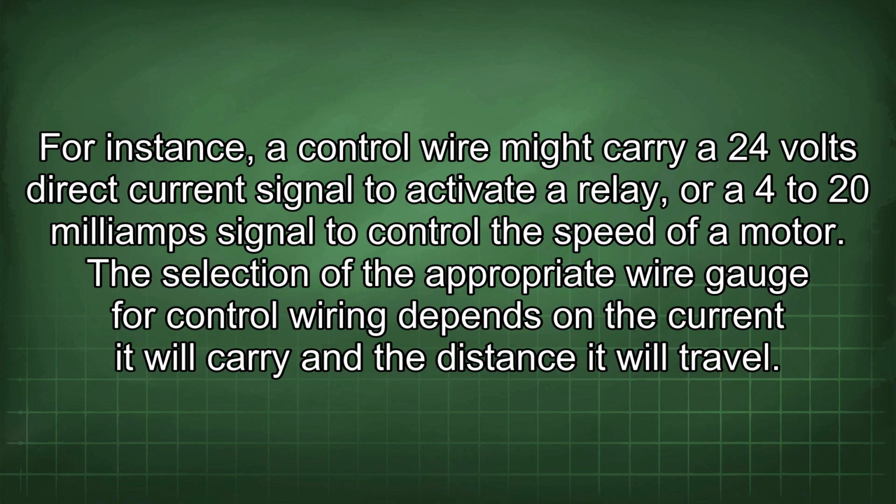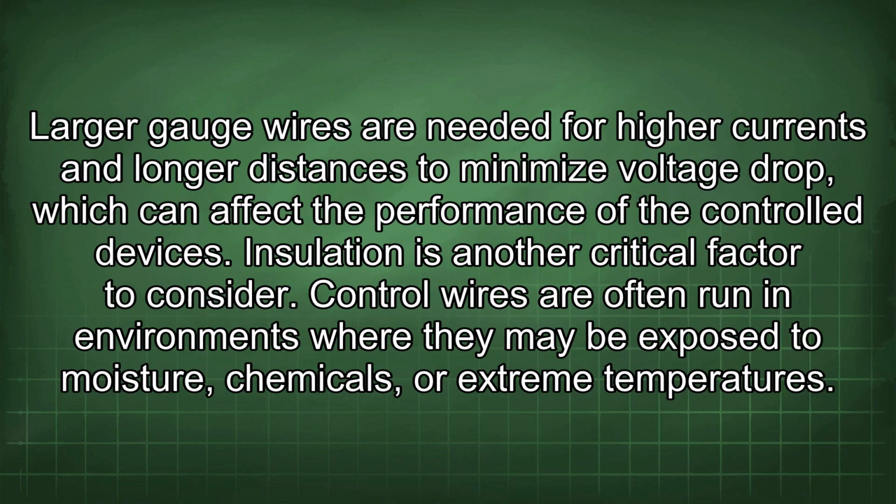The selection of the appropriate wire gauge for control wiring depends on the current it will carry and the distance it will travel. Larger gauge wires are needed for higher currents and longer distances to minimize voltage drop, which could affect the performance of the controlled devices.